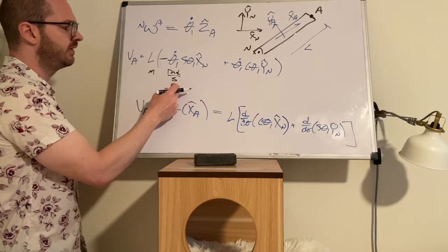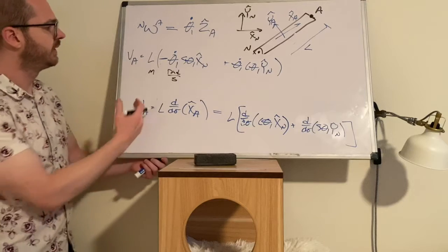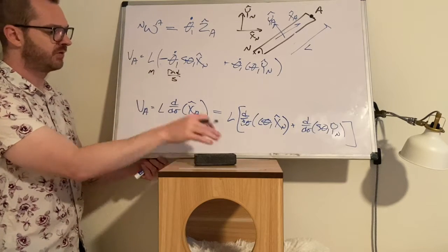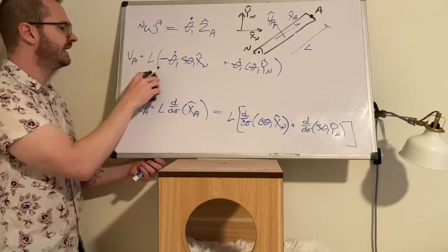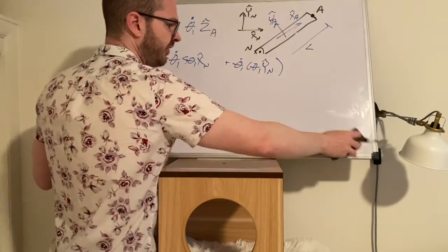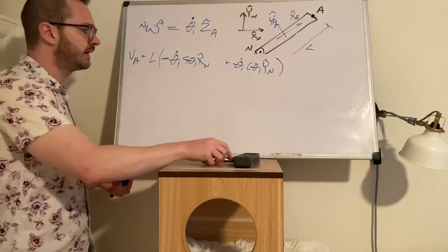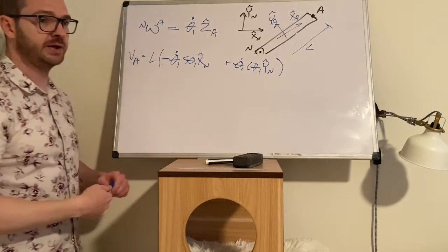And when you multiply these, you lose the radians because the radian is just the connection to the arc length, and then you end up with meter per second. So that is going to be a linear velocity. We're not quite done with it yet though. We can clean this up a little bit. First of all, recognize that we can factor out the theta 1 dot.